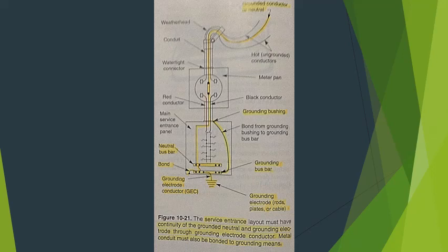In addition to or in place of the water supply pipe, other grounding electrode systems shall be used, like metal frames of buildings, metal electrodes encased in 2 inches of concrete within or near the bottom of a concrete foundation, or 20 feet of 2 AWG bare copper wire buried not less than 2.5 feet below the surface.